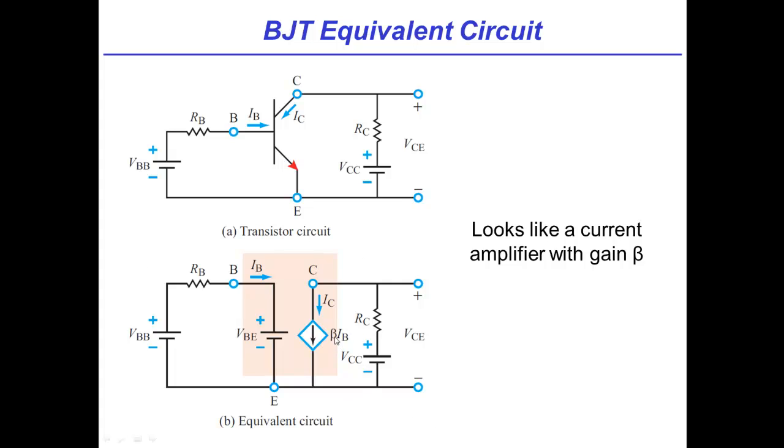It's quite common to have betas of 200 to 300. In fact, even more than that is possible. Okay, so what you're saying is, let's say a milliamp was being fed to the input. You're talking about a reasonable fraction, a tenth of an amp, coming out the output. It could be 100 milliamps, a couple of 100 milliamps. It depends on the beta.